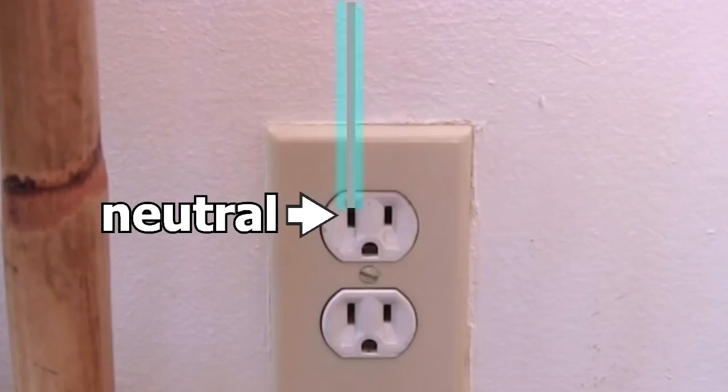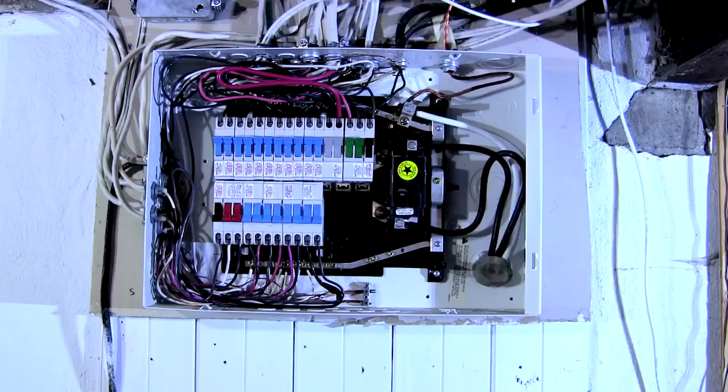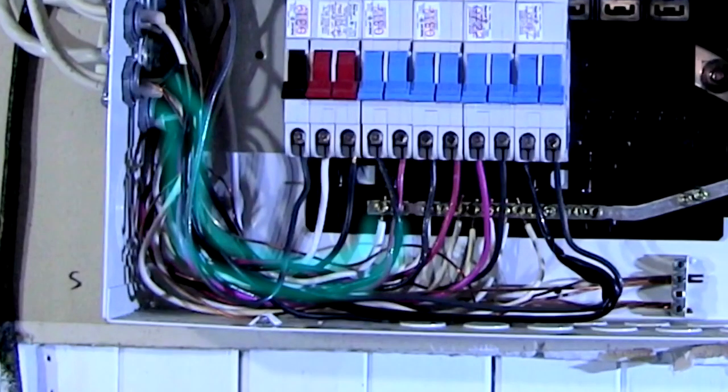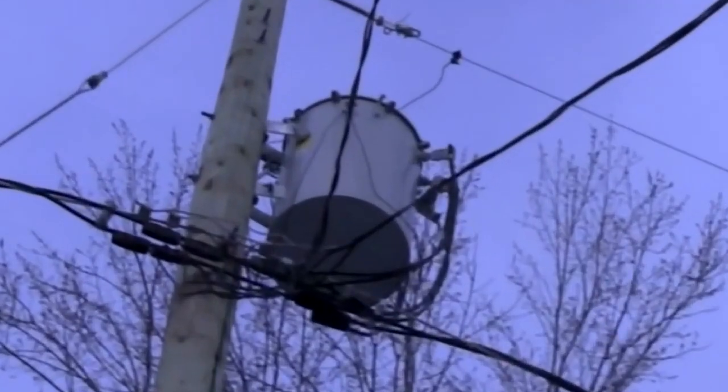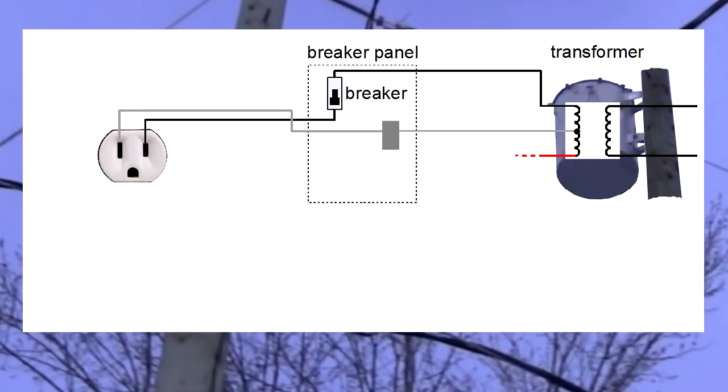The other hole, again called neutral here in North America, also goes to that breaker panel, but not to any breaker. Instead, it goes to this metal bar. From there, the electricity goes along this thick white wire, and then outside your house to the same transmission pole and the same transformer. Here that all is in a diagram.